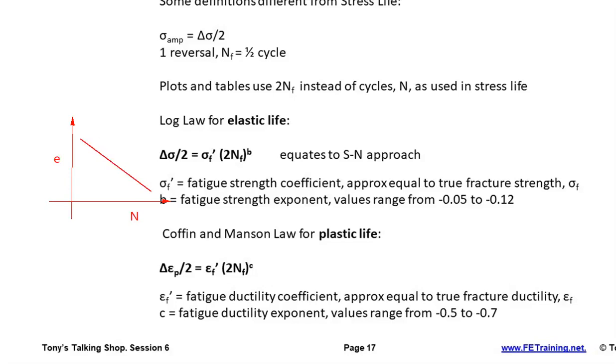They did that, and they took out and said the plastic bit related to the life to failure. If we could actually come in and work with that, then we've got a prediction of our life. But that's a real pain. You've got to go in and produce plastic strain only. So that's kind of like half the story. Now this is why it's recast in terms of strain, because we're talking about a strain amplitude, number of cycles. You can think of it as like an equivalent to SN, but it's basically going to be just plastic strain on its own. So that's going to be half the story.